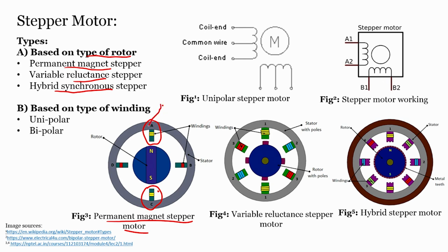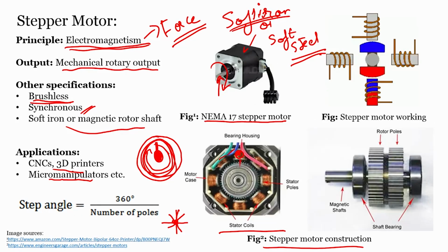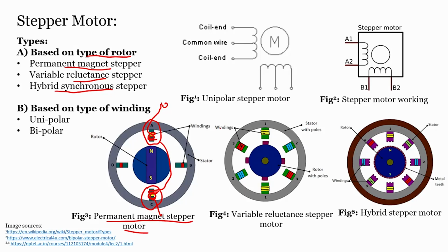The cable comes, rotates about this stator pole, goes here, rotates about this one and goes out. So what happens is, one coil, say the green one that we saw in the previous slide, the green and blue are close, and red and black are close. I am just telling you an example. The green wire will come here, rotate around the pole, go to the other pole, rotate around it, and go out as, say, the blue wire. Similarly, a red cable will come from here, go about this B pole and come out as the black wire.